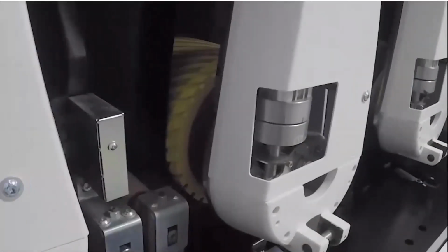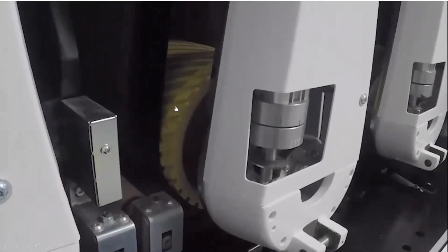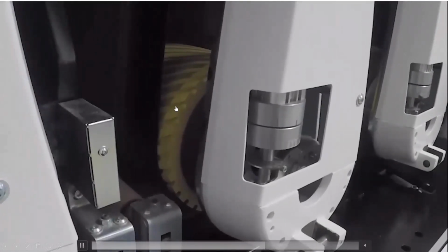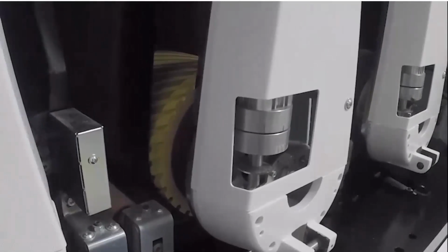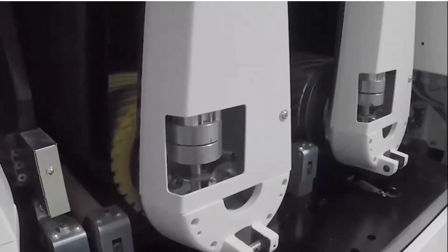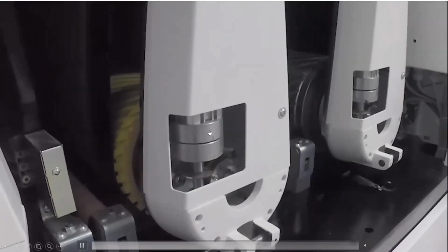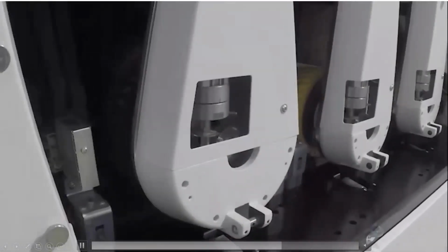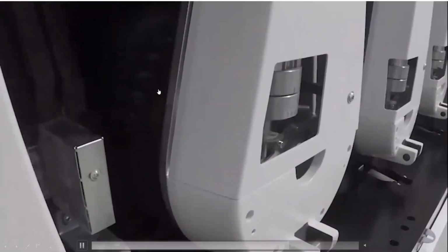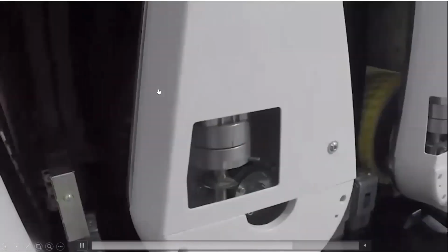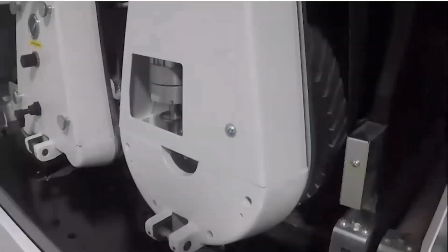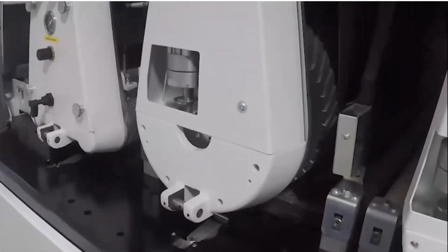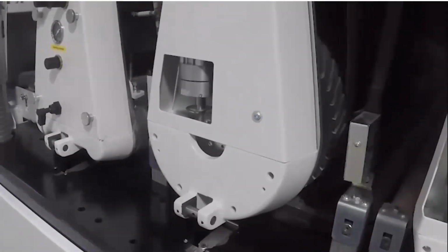So on our second head, this is the 85 Shore rubber drum. Our first steel head is the workhorse inside of the machine. Head number 1 is doing about 70% of the stock removal. We also have our grit compensation. Again, depending on which grit, or a paper belt versus a cloth belt, we can set that thickness. Head number 3 is a 55 Shore rubber drum. And the purpose of the rubber drums is, again, just to get out those deeper scratches and give us a more soft scratch with the appropriate grit.